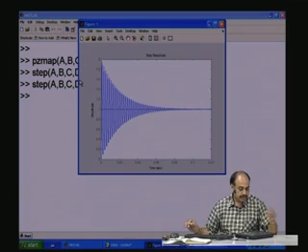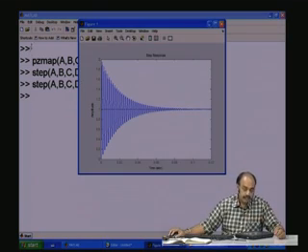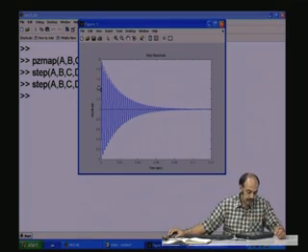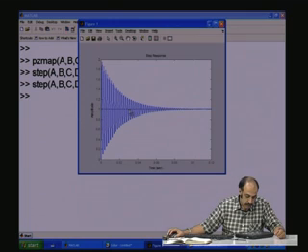So, let us see the step waveform. As I have been telling you, for a unit step input, you see the output voltage across the capacitance, you see the oscillatory nature of the voltage here, and then gradually it damps down. You see that the amplitude is gradually decreasing. This implies the loss in the resistor, and there is a time constant involved in that.